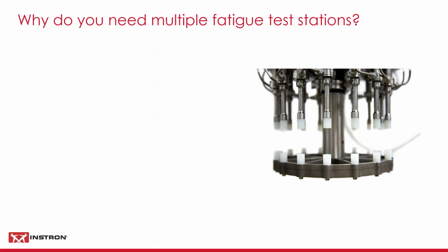So you insert each one into its station in the carousel and then make a very fine adjustment so that you get a preload which is the right level. We're going to be talking a fraction of a Newton. Out of shot in this image, up above, you have an insertion point for something like an Allen key, and you'd make a very fine adjustment, with a very fine thread, allowing you really good control on each one of the preload and the location on each stent before you start the test.